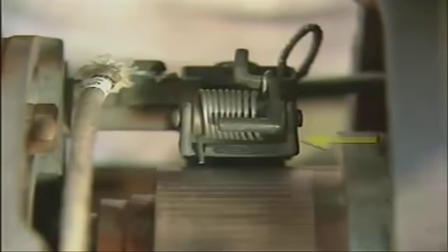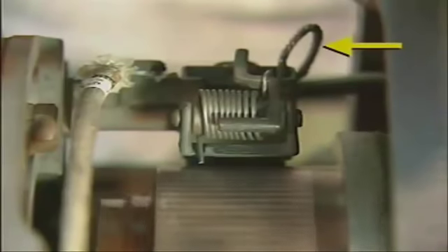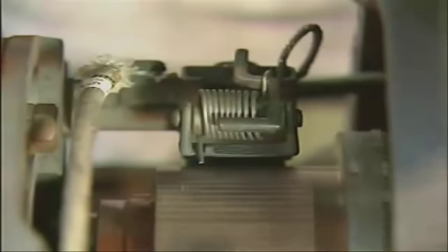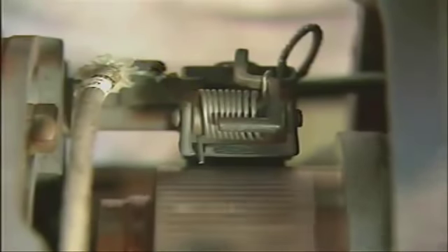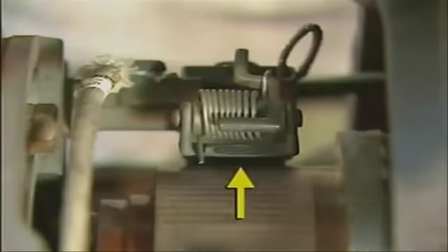This contact may not be possible if the brushes are hung up in the brush holders, if the brush pigtails bind on the brush holders, if the brush tensioning devices are set incorrectly, or if the brushes are too short. Full contact between the brushes and the commutator is also impossible if the brushes are broken, cracked, or chipped.